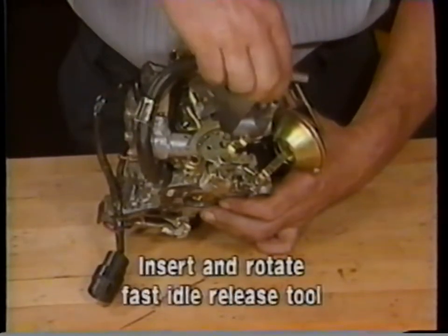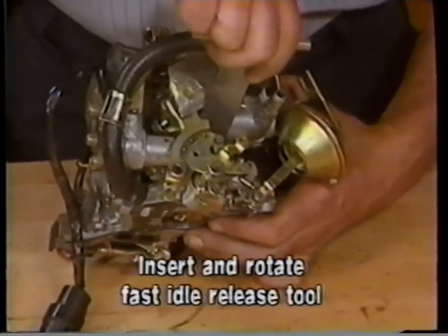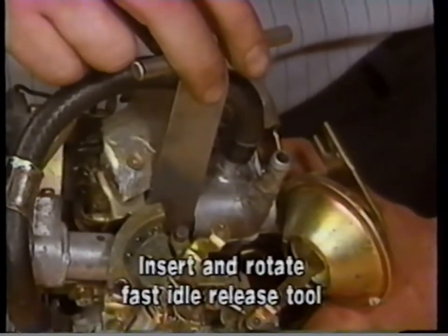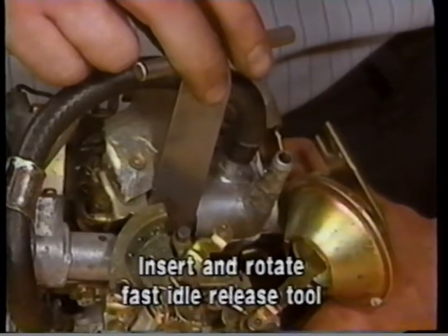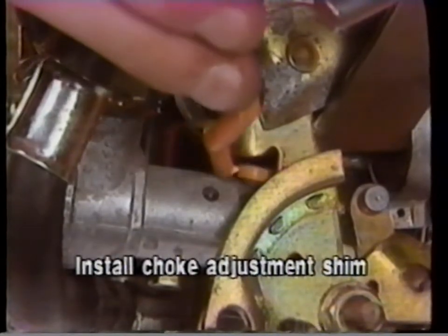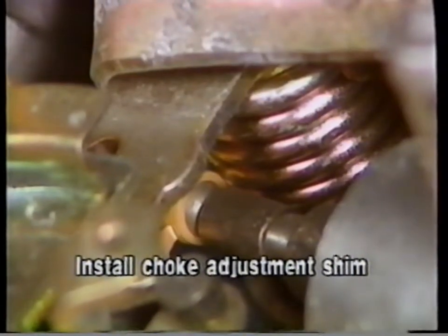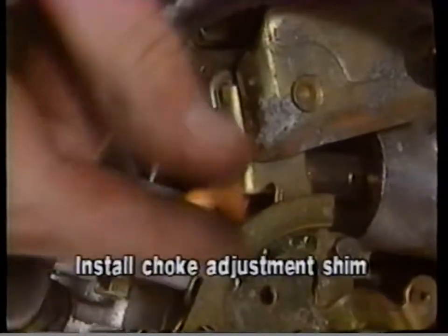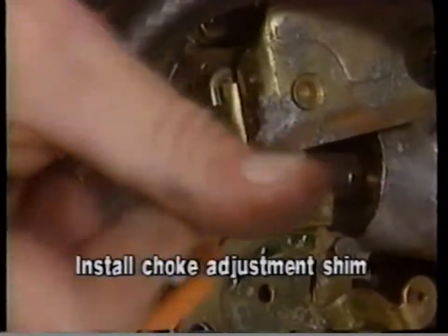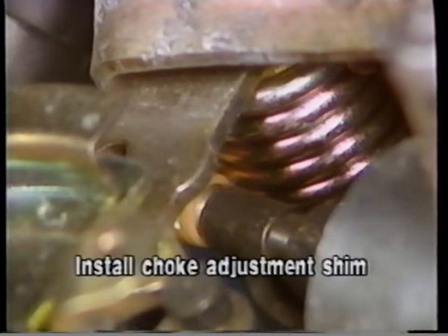With the carburetor on the bench, insert the fast idle release tool between the fast idle cam lever and the wax element housing. Turn the fast idle tool counterclockwise about 45 degrees to provide a clearance between the choke adjusting screw and the plunger. Using the installation stick attached to the choke shim, install the shim on the choke adjusting screw as shown here. Now, rotate the fast idle release tool clockwise and remove it from the carburetor. Next, detach the installation stick from the shim by twisting the stick and breaking it off. Ensure that the choke adjustment shim remains securely installed between the plunger and the adjusting screw.